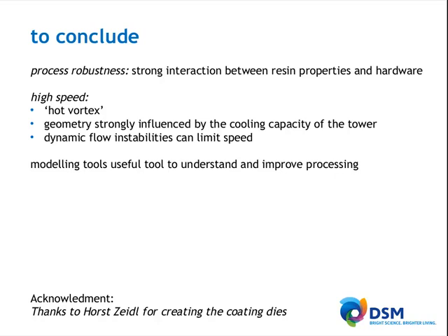Okay, thank you. Next question: should the primary coating temperature be set higher than the secondary to better match their viscosity? I have to think about that for a second. Sure. Especially with these interface instabilities, of course we know that if you keep the rheological properties of the two resins the same, you will not see any interface instabilities. So if temperature is one way to govern that, that could be an option indeed.